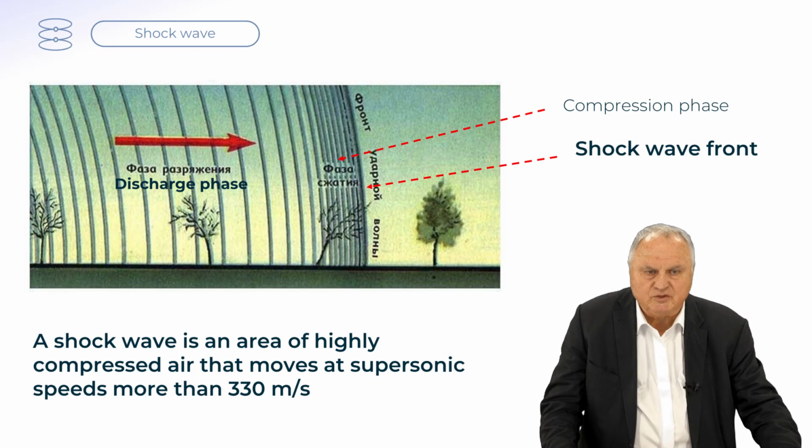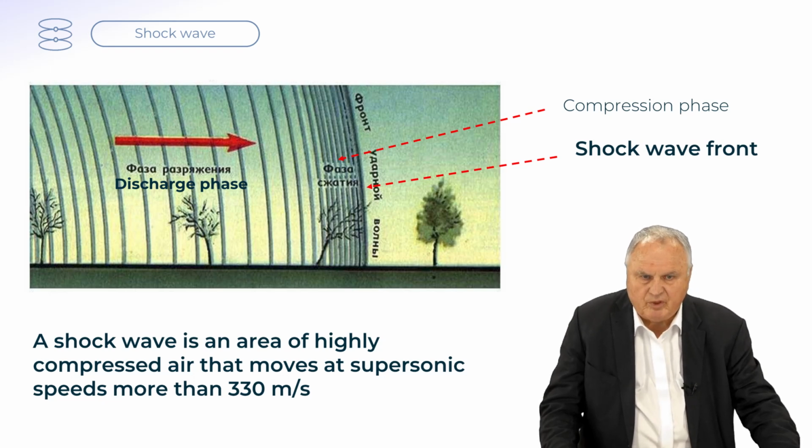The amplitude of a strong wave, as created in air by an explosion, decreases almost as the inverse square of the distance until the wave has become so weak that it obeys the laws of acoustic waves. Shock waves change the mechanical, electrical, and thermal properties of the compressible material. Let's look at some pictures.